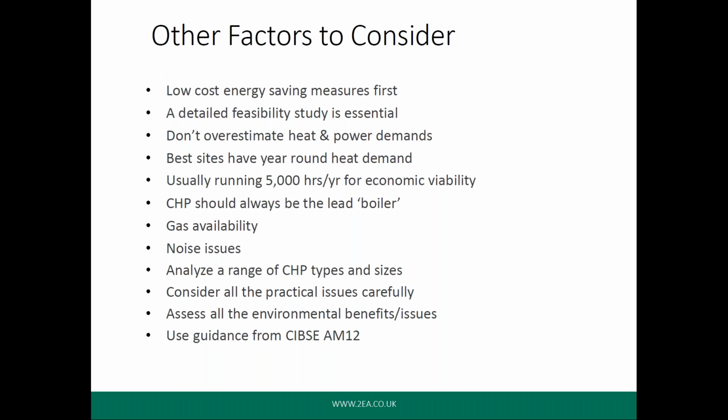One way that low gas pressure can manifest itself is starvation of the combined heat and power unit on cold winter's days. Pressures may have been measured or calculated when no boilers were firing or when consumption was low, so on a really cold day, the combined heat and power unit can see a reduced pressure, which can cause operational problems. Another point to note about gas is that a combined heat and power unit producing 300 kilowatts of heat takes more gas than a boiler producing 300 kilowatts of heat. Now, this might seem obvious, but I have seen instances where it clearly hasn't been. The simple rule of thumb is the gas required will be approximately 3 times the electric output of the combined heat and power unit.